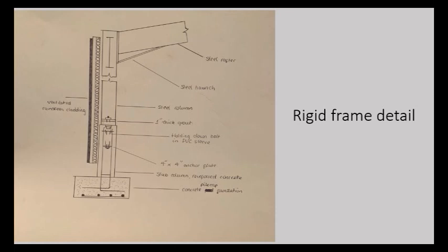The structural frame chosen is a rigid steel frame, but will consist of a stub column made from reinforced concrete. The steel frame will sit on a pile cap foundation, as this is generally the type of foundation used for steel frame buildings. The pile cap will be at suitable depth on a bearing stratum. The concrete foundation will support the stub column, which has the column holding down bolts cast into it.